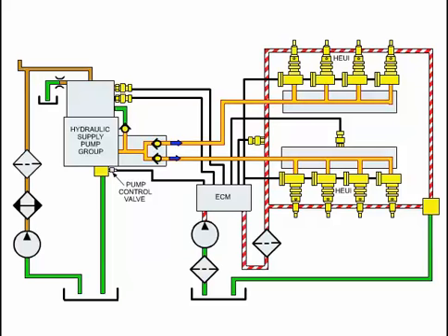Oil from the hydraulic pump enters the two oil supply passages, which convey oil to the injectors in the two-cylinder heads. Reverse flow check valves are used to prevent pressure surges between the oil passages on opposite banks. This effect can be compared to water hammer on a domestic system. The oil supply passages are connected hydraulically to the injectors by jumper tubes. Oil used by the injectors is released below the valve covers and drains back to the sump through the pushrod compartment.